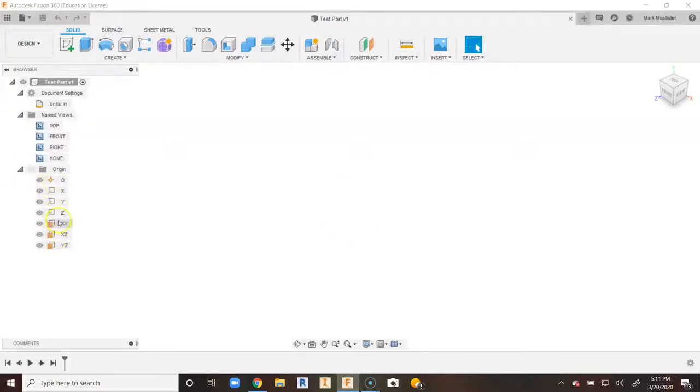If you're going from Inventor to Fusion, you're going to see a lot of similarities in this particular folder. First thing we want to do is go to units, and if we just leave our mouse up around units, you're going to see a little pencil right here. Let's just change the active units, and we can change to whatever units we are currently designing in. For the sake of this video, we're just going to go ahead and stay in inch.